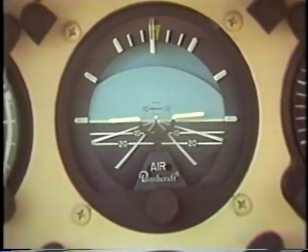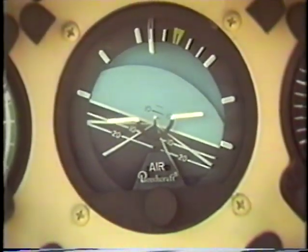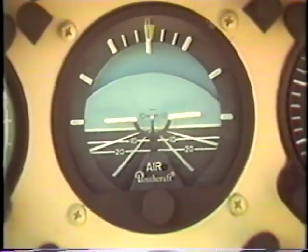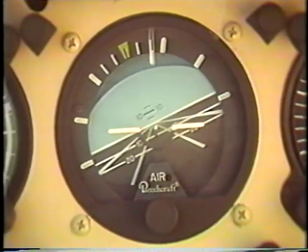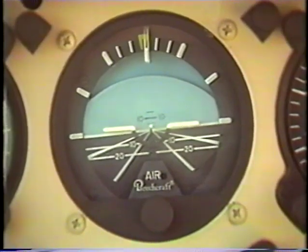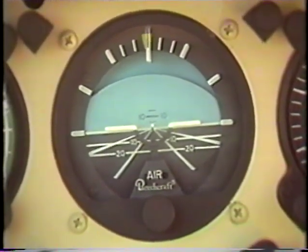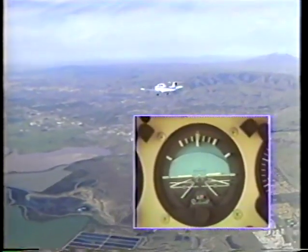It consists of an airplane silhouette fixed to the face of the instrument and therefore aligned with the airplane itself, and a graphic representation of the horizon which is attached to the gyro. So when using the attitude indicator, the horizon remains stable as the airplane moves around it. The airplane on the attitude indicator moves with the real airplane to which it is attached.